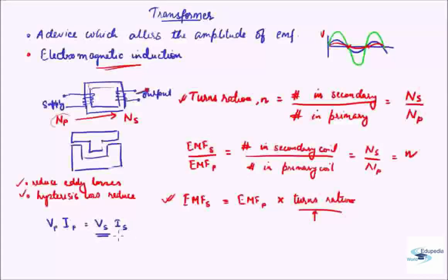Okay. Now a larger current means a thicker wire is required in order to avoid overheating. Therefore, in a step up transformer, since the secondary coil will have higher voltage, the current will be lesser in that, therefore the primary supply end should have thicker wire.